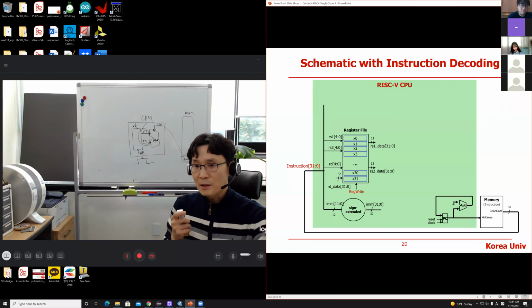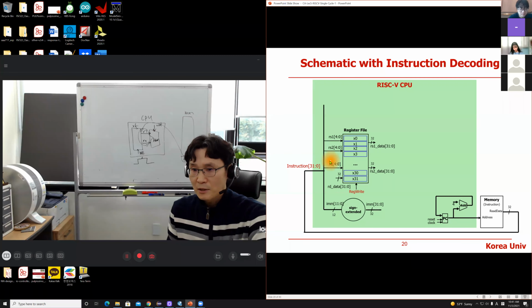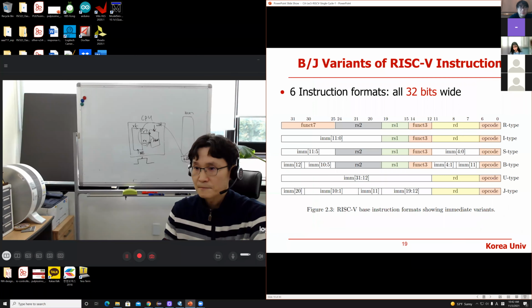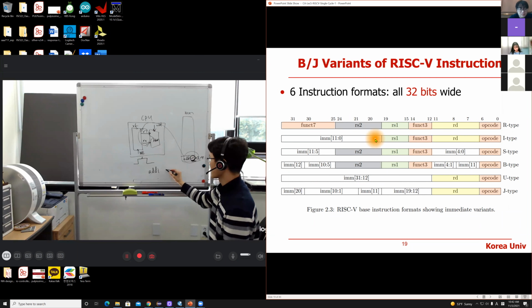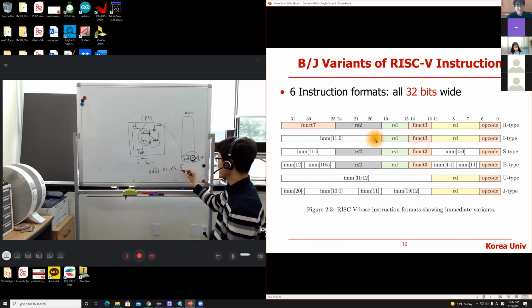And then depending on the instruction, you need to do sign extension. An example is the case of an I format instruction. Look at the second source operand. To give you a better view, take an ADDI instruction: X2, X3, some constant, some immediate.